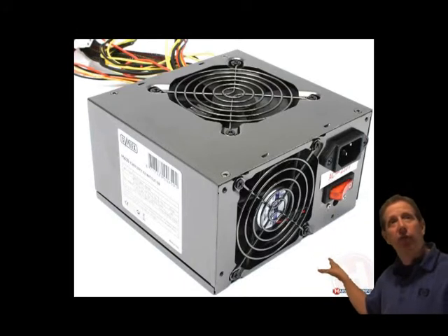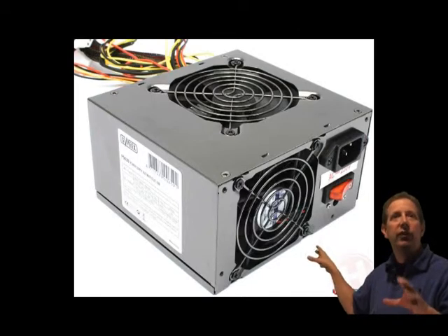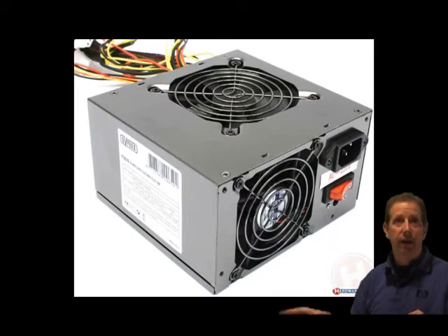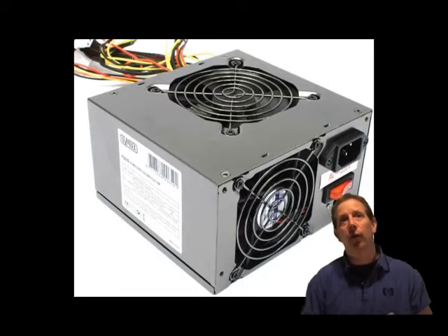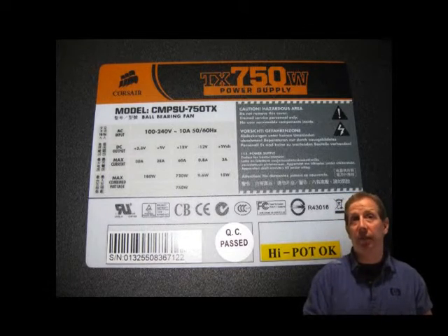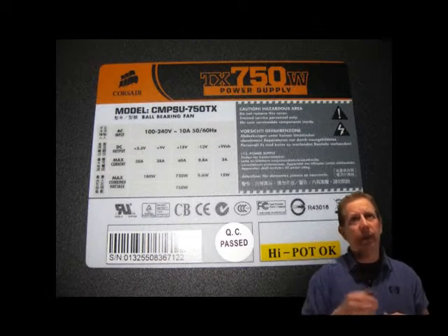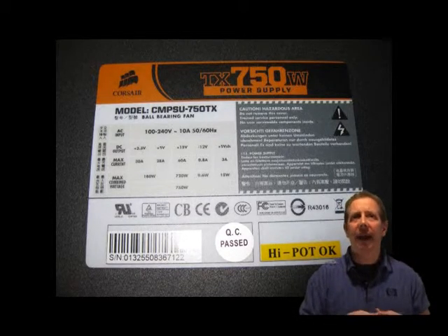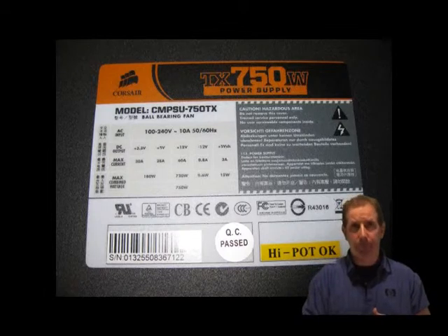Now, when selecting a power supply, pay particular attention to the capacity for the 12-volt rail. A rail is a term used to describe each voltage line of the power supply. The positive 12-volt rail is the most used, especially in high-end gaming systems. Sometimes you need to use a power supply with a higher wattage than the needed average.